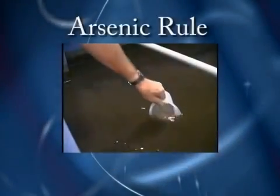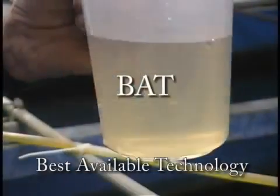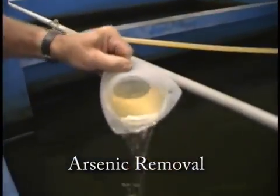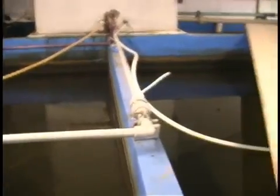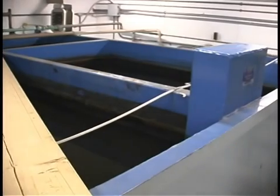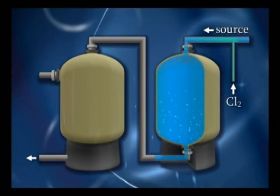For the arsenic rule, EPA evaluated several technologies as candidates for Best Available Technology, BAT, for arsenic removal, including conventional iron and manganese removal. During the iron and manganese removal process, iron and manganese are oxidized to form insoluble precipitates that are subsequently filtered out.